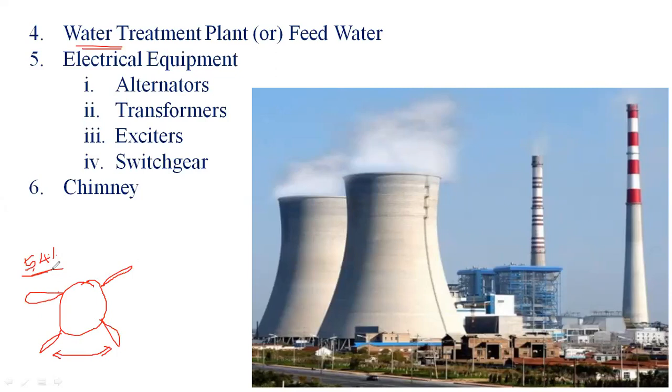And the water we have taken is from the river, lake, or canal, with dissolved impurities and dissolved gases. Generally, in a thermal power plant, we need to supply DM water, that is demineralized water, or RO water. The available water is raw water, which we could directly send to the boiler with the help of the feed water.